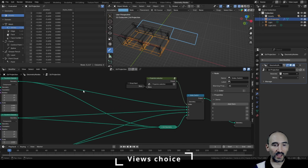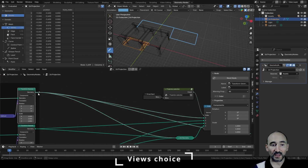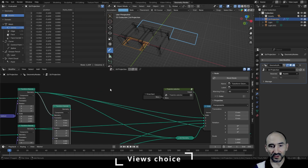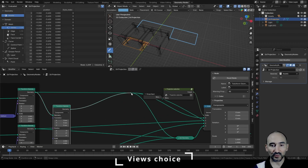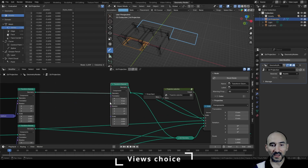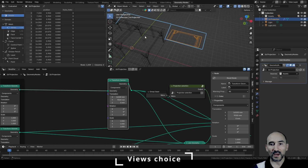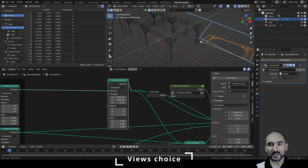So to do this, we can take the right view, so this view here, and we can add another transform geometry. So if I link these in a transform geometry, I can press Shift right drag to create a reroute and link this output to this reroute. And now here we need to translate this object on the X and on the Y because we want this object here. But as you can see, the correct point is this point here, okay?